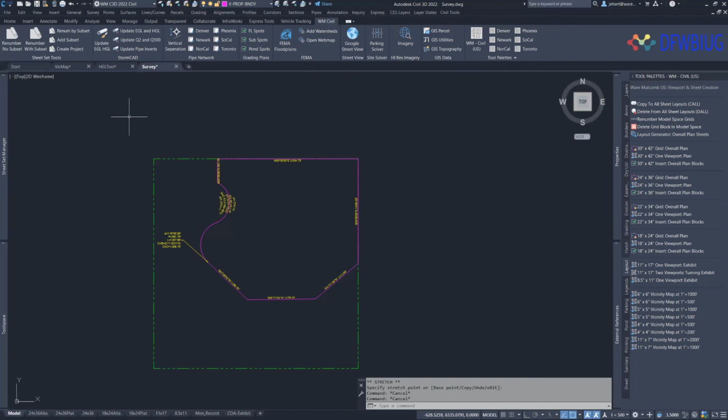If your municipality works with a lot of keynotes, you could automate keynotes, because we don't have that like AutoCAD Architecture does, the keynote function. But you could add them as a subset to your sheet set, and then your labels could be fields. And as you update those sheet sets, you could remove or add them quickly. Create a table, a table legend for that.